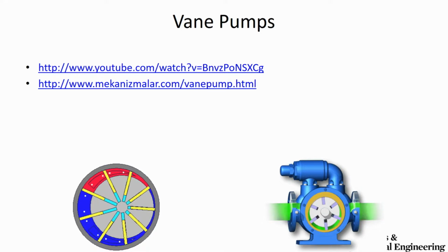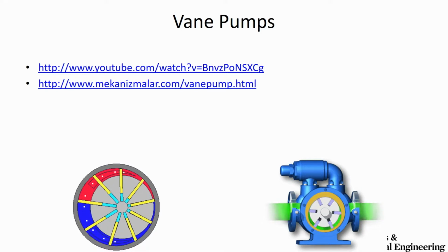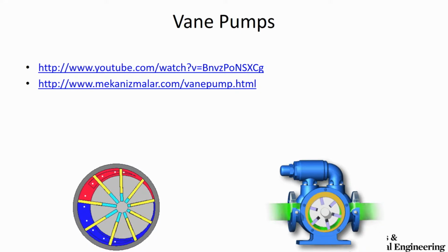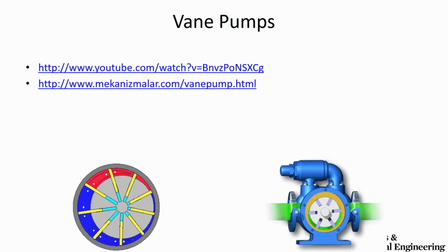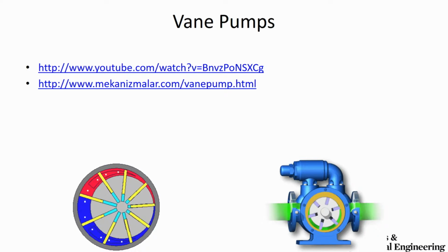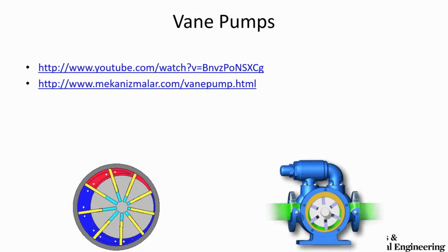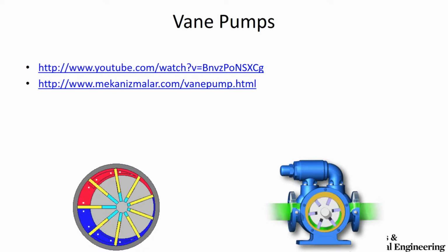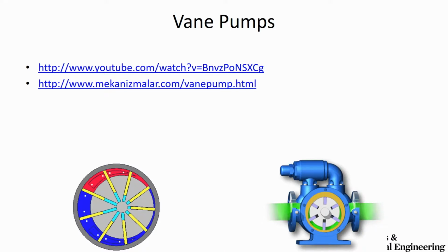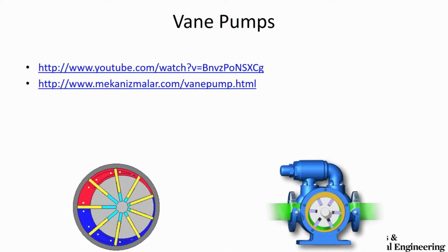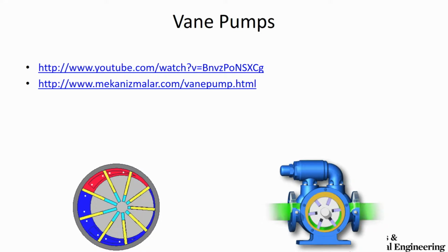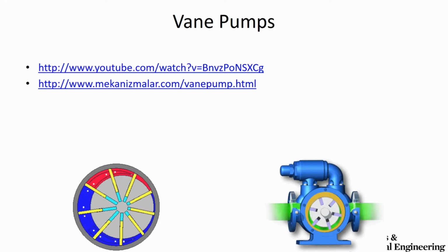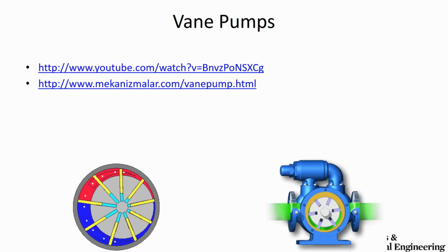Okay, so those are vane pumps, and again, these can be used somewhat as motors, but not as common because we often rely on centripetal force to keep those vanes out against the outside housing, so that they're sealed out there. So they're going to have a minimum rotational speed, and if I try to push fluid into them, I can actually push the vanes into the disc and break the seal there. So it's a little bit more complicated in terms of how they operate and their operating parameters, what the minimum speeds are and so forth. That's a vane pump there.